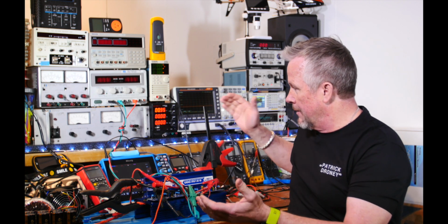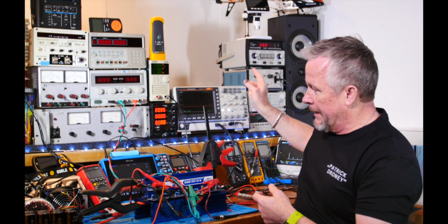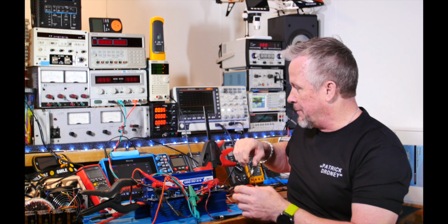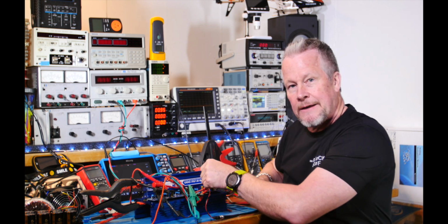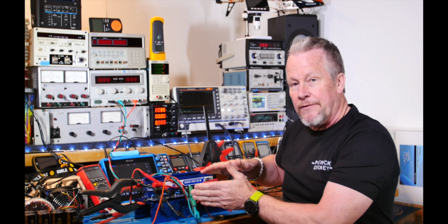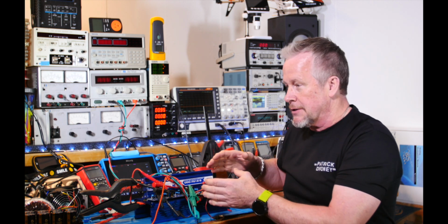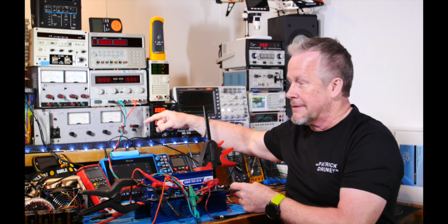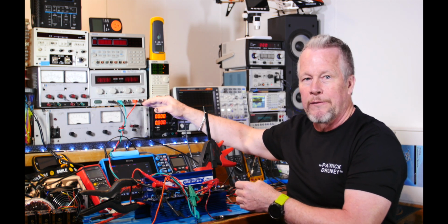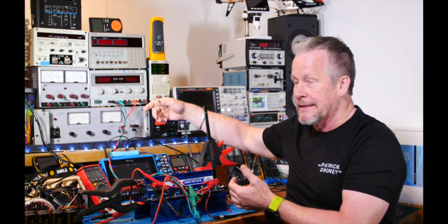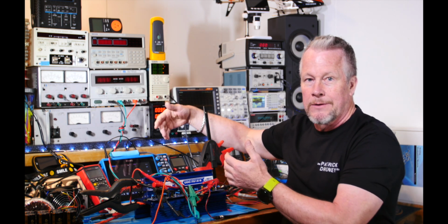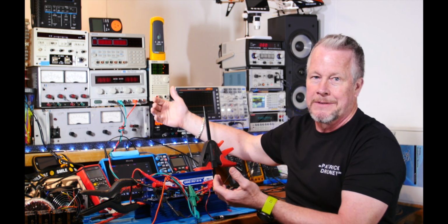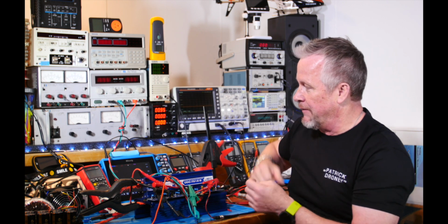Now, we didn't see any problems like that. We didn't see a lot of distortion from the generator, especially at the levels we're using. But what happens is when you're setting this current here, and you set it for a higher current hoping to lower the distortion, the problem is this power supply is seeing those peak currents. It's not seeing the average 1.5 amps or 1.6 amps. It's seeing 3.5 amps, or 4 amps. It's seeing higher than what it is supposed to put out. It just doesn't have the bulk capacitance.